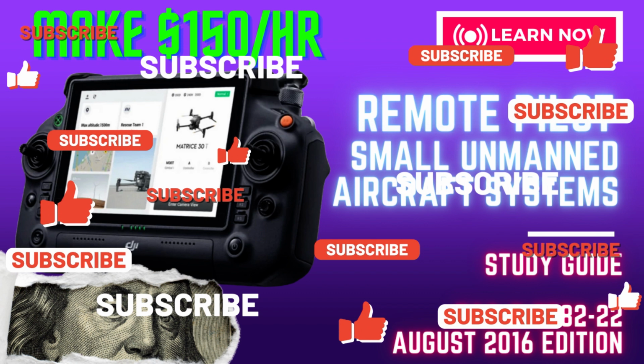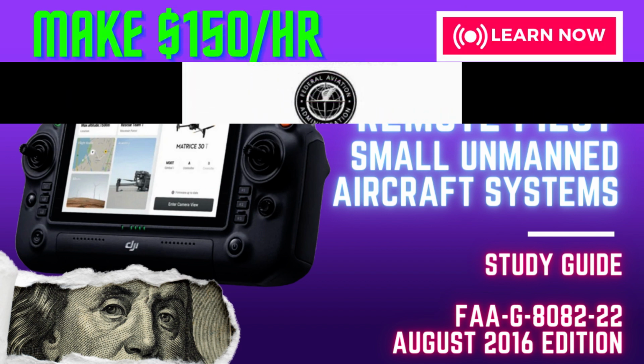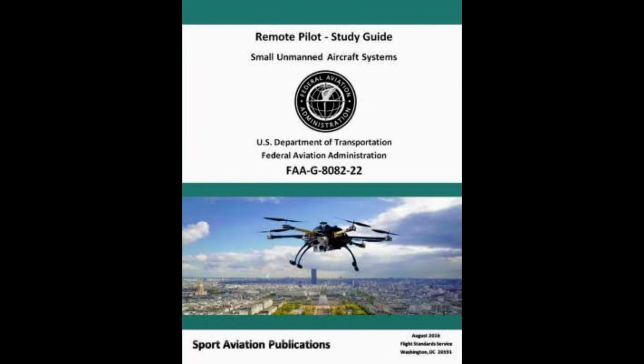Before any flight, the Remote Pilot in Command (PIC) should verify the aircraft is correctly loaded by determining the weight and balance condition of the aircraft. An aircraft's weight and balance restrictions established by the manufacturer or the builder should be closely followed. Compliance with the manufacturer's weight and balance limits is critical to flight safety. The remote PIC must consider the consequences of an overweight aircraft if an emergency condition arises.